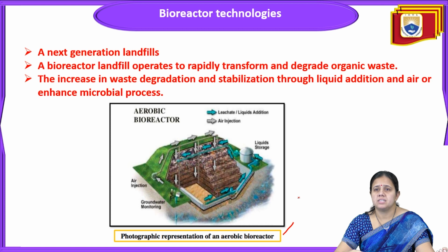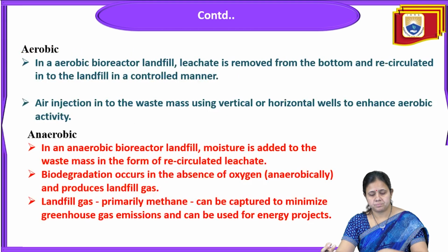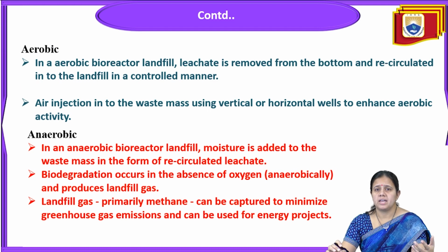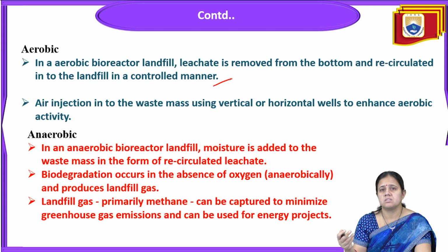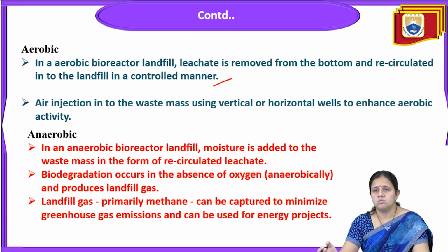This anaerobic bioreactor rapidly transforms and degrades all the organic waste. The increase in waste degradation rate and stabilization through liquid or air addition enhances the microbial process. So, aerobic and anaerobic. Aerobic bioreactors in landfills remove the leachate from the bottom and recirculate it into the landfill in a controlled manner.